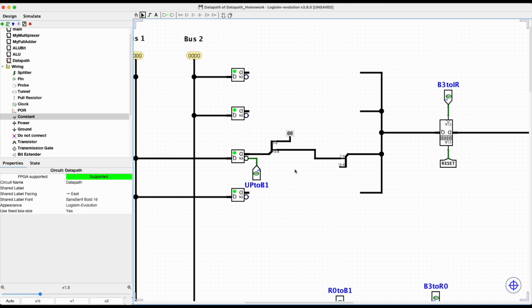Okay, so you'll want to look at the target address. You're going to look at a jump instruction right here. For the signed immediate, you'll probably look at the add immediate instruction. Now remember, you don't have to do the adding, we just have to get the immediate onto the bus. Your ALU will do the adding.